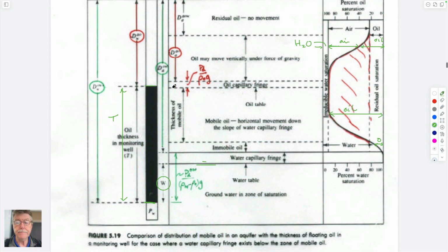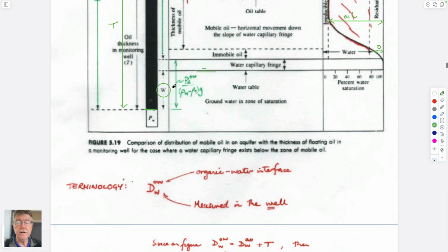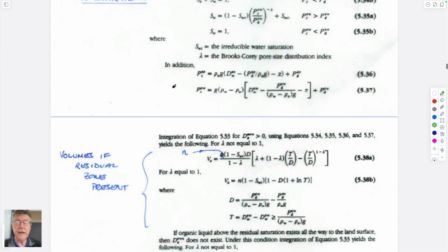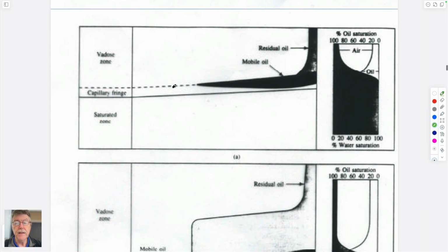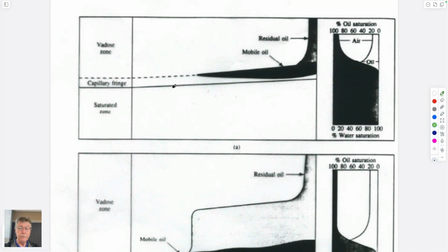Now it's time to do the kinds of things we want to do. I made the point that this is a complicated analysis, but it's for fluid sitting on top of the water table. The other point to make, very briefly, is that one way you can get smear, not just in the column as it transited down to the water table, is by that puddle separating out, sitting on top of the water table and spreading.